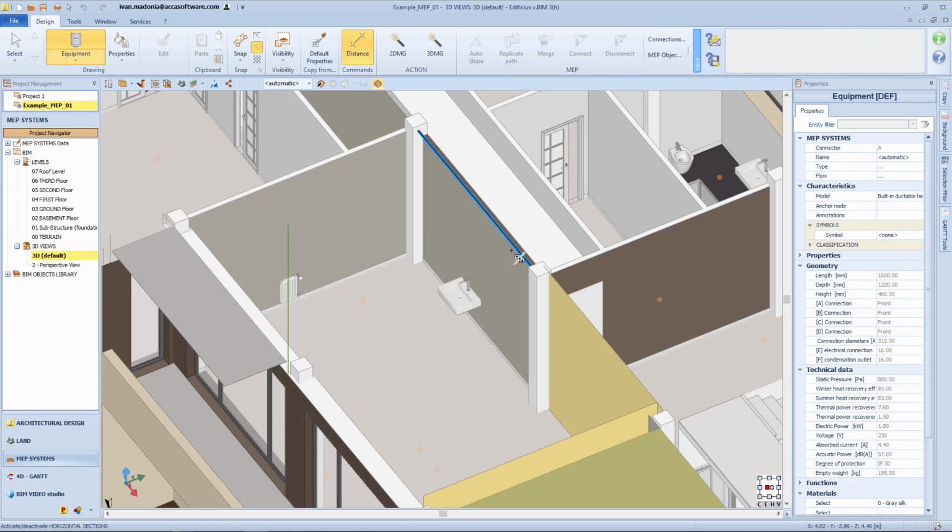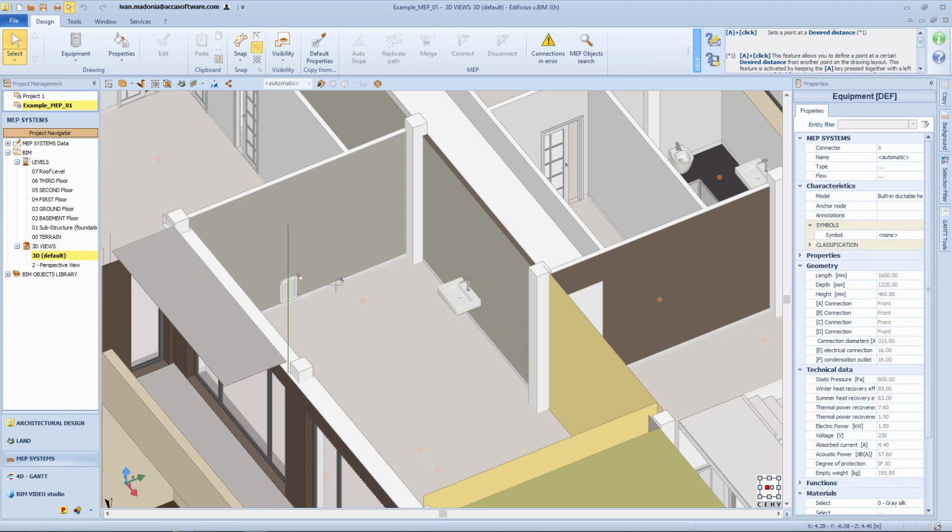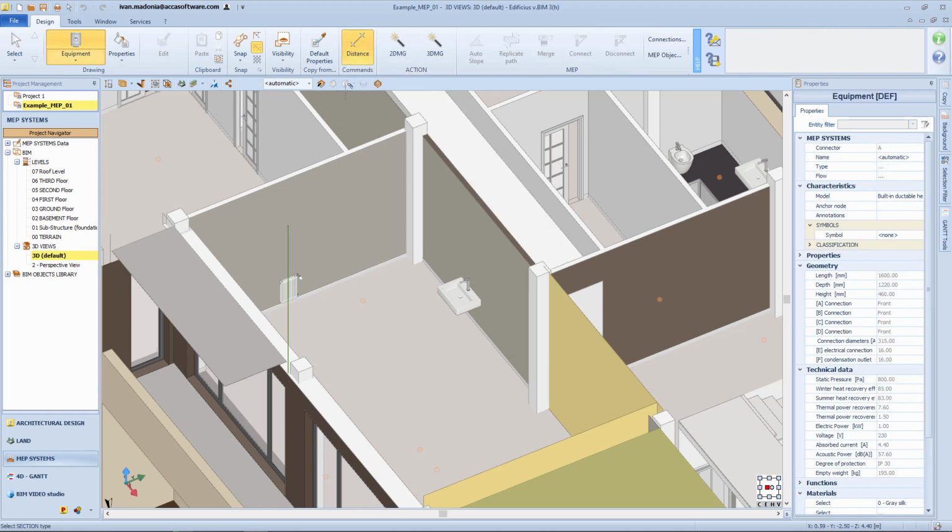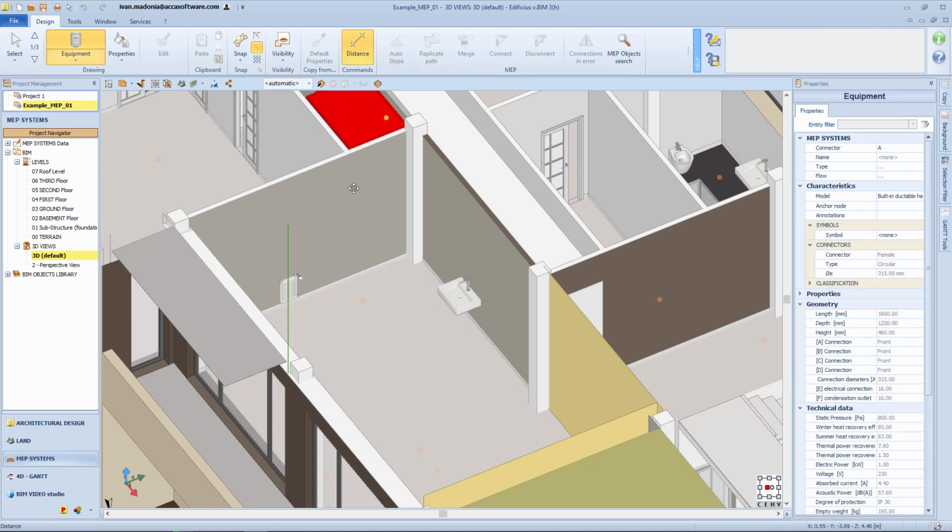On a level view or in 3D, the activation of this functionality is presented as a support tool for the positioning of MEP entities on the drawing. For example, an entity of type equipment is activated for insertion and then the distance option is selected. Taking advantage, if necessary, of the point or linear snaps of the drawing, with a click you choose a reference point, starting from which a blue line is activated that joins this point and the anchor point of the MEP entity. The line color varies if you recognize displacements in the directions identified by the axis or vertically or horizontally.